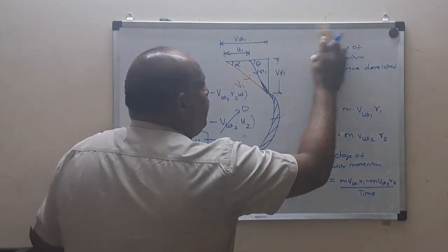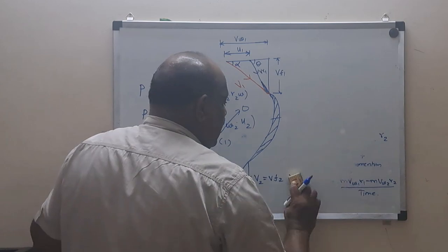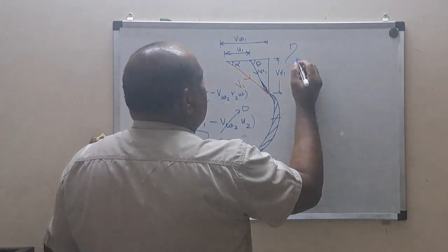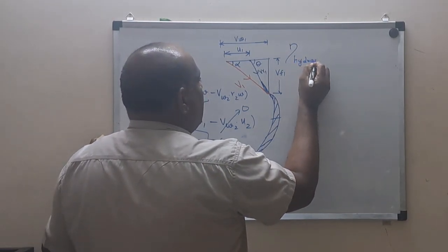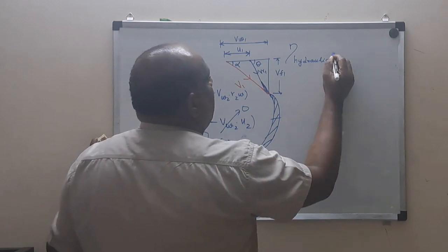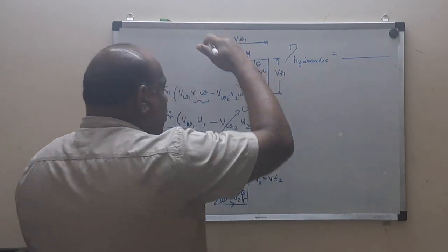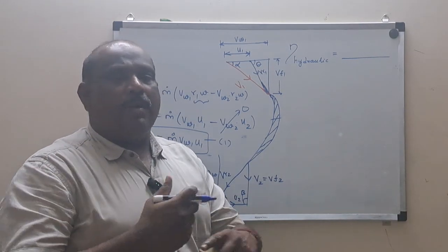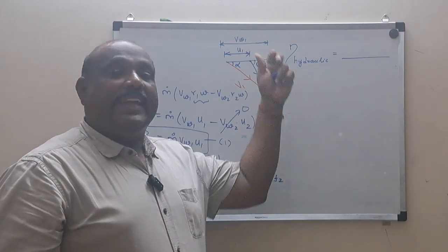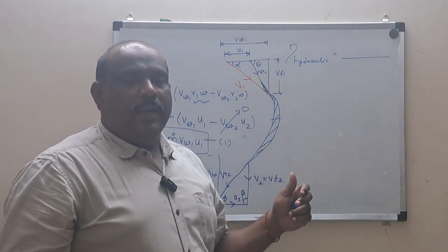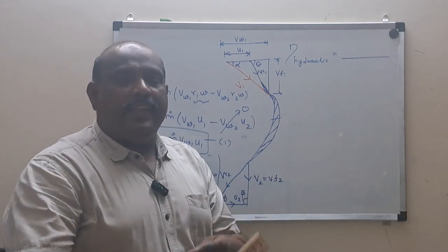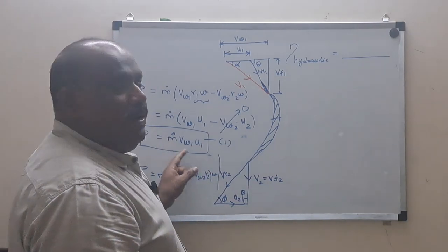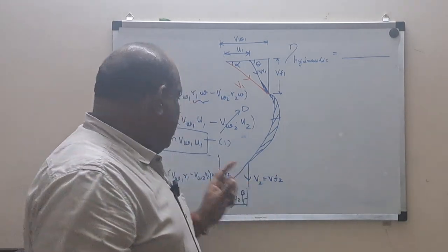Okay, nice. Now let us define what hydraulic efficiency or manometric efficiency is. What is the hydraulic efficiency? How much water is coming and hitting the blade, and because of that, how much is the shaft rotating? So the input is the head available, the manometric head available. The output is what? How much is able to rotate the turbine blades? That is the outcome. Got the logic? So the output power will be this one. How much work is done? What is this power term?